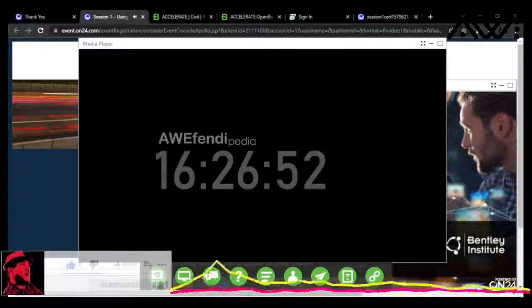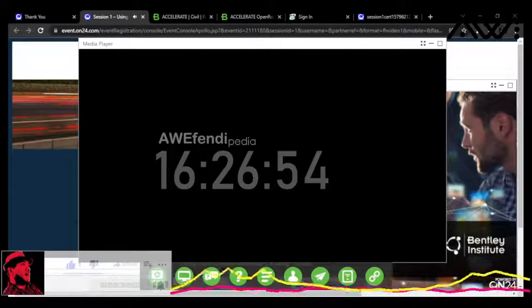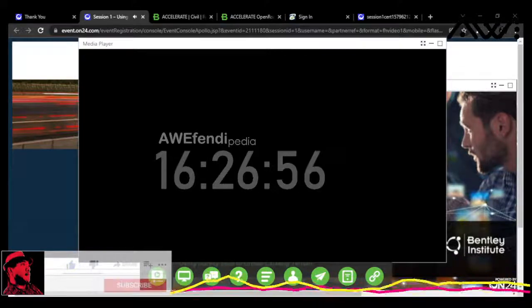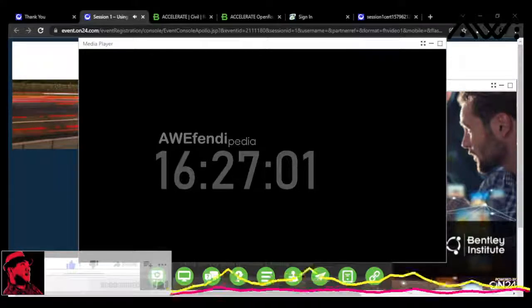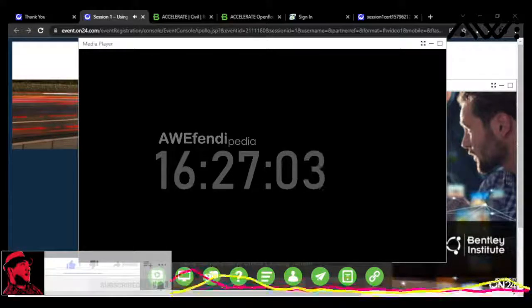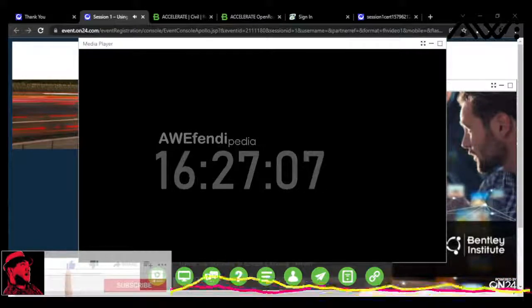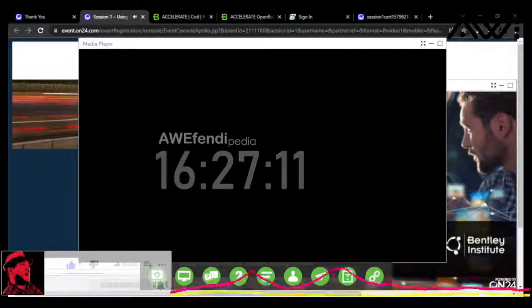So if I move it down, we can see the element changing there as that point is now in a different location in that line string. So now that I'm not relying on link codes, but I'm using a point list, it's allowing me to do some different types of edits in which the order in the field book is not as important. So a lot of flexibility there. Just wanted to show those two options in doing our editing.